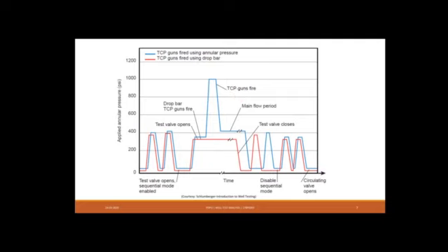as TCP requires large pressure to fire the detonator. But if drop bar is used, it is dropped from high potential. Thus, TCP can fire the detonator spontaneously. Thus, the change in the annular pressure will be minimal. After the detonation of the tube, the flows are taken and the pressure data are recorded. And after the completion of the flow, the test valve closes with the help of battery and other electronic equipments. Simultaneously, the circulating valve opens and the tool can be retrieved.